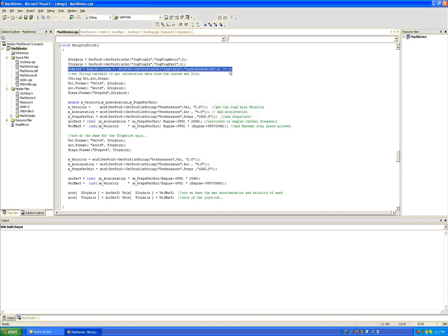Same thing with enabled. With enabled, I am asking Mach3's XML file, has this person enabled this joystick plugin? If he hasn't, don't jog with it. If he has, remember it. And I remember it by writing those variables into the XML at some point during the run. During the setup of the joystick, I don't write anything, of course. I'm only interested in reading variables from the XML.